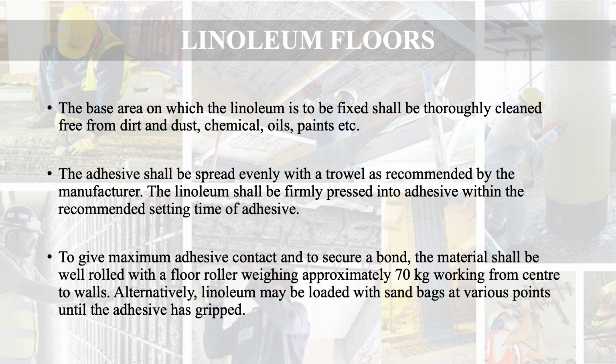To give maximum adhesive contact and to secure a bond, the material shall be well rolled with a floor roller weighing approximately 70 kg, working from center to walls. Alternatively, linoleum may be loaded with sandbags at various points until the adhesive has gripped it.